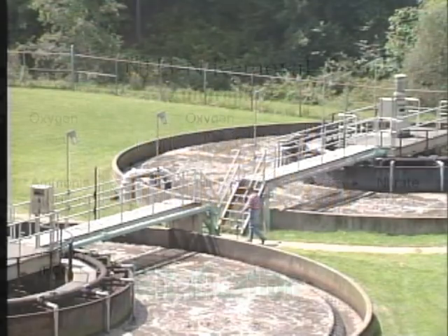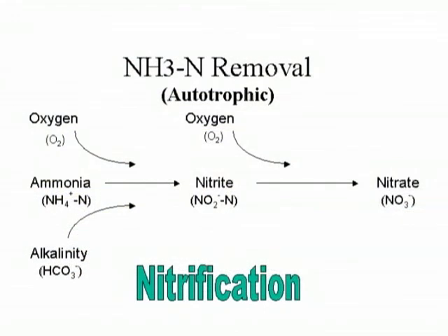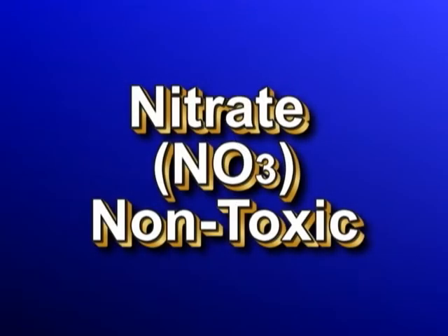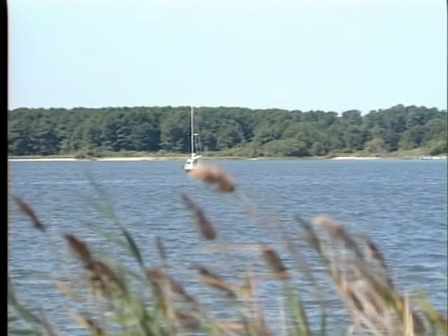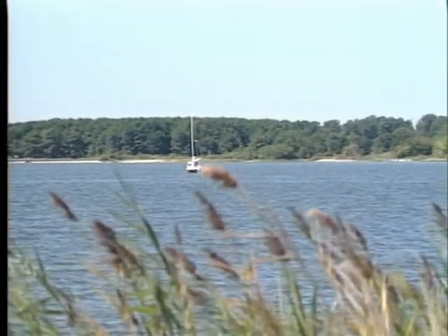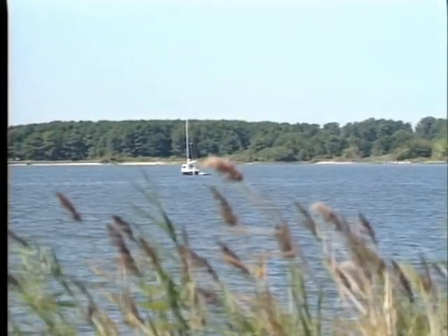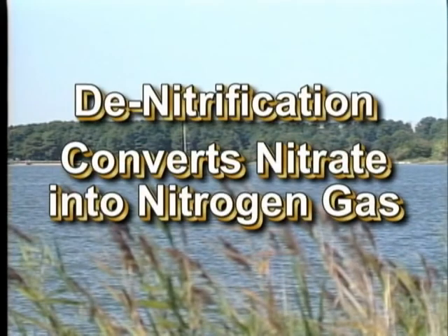Nitrification is a multi-step process utilizing autotrophic bacteria of the genera Nitrosomonas and Nitrobacter to convert the ammonia in the wastewater to nitrate. When ammonia is converted into nitrate, the nitrate is non-toxic. However, nitrate can serve as a nutrient in water. In many cases, especially in the Chesapeake Bay watershed, nitrate must also be removed from the wastewater as well through a process known as denitrification.